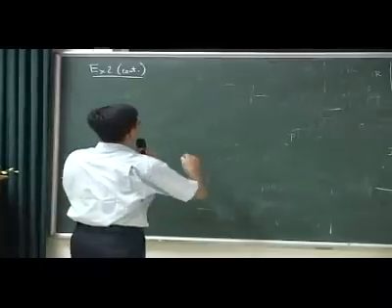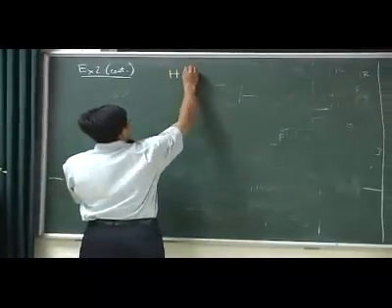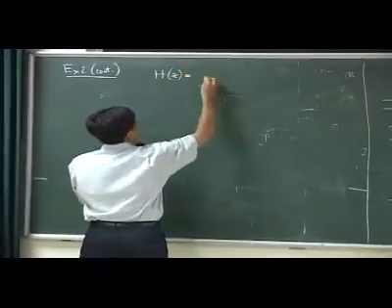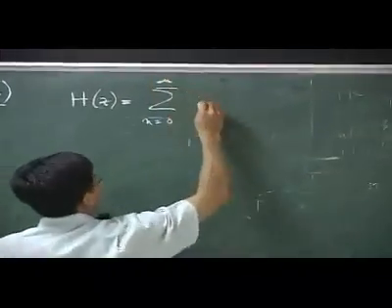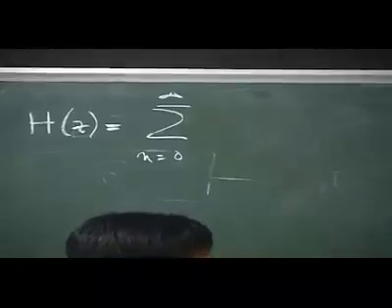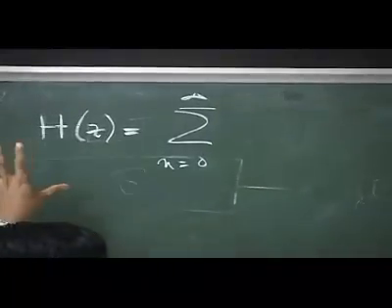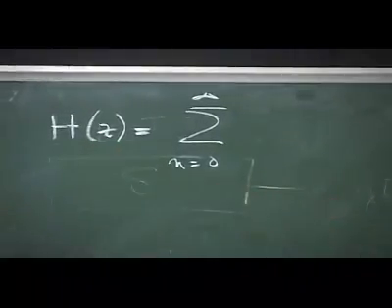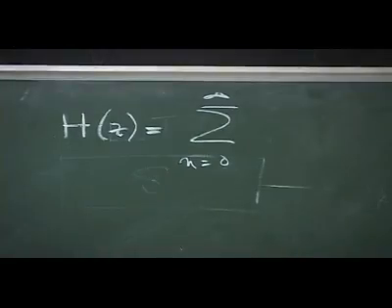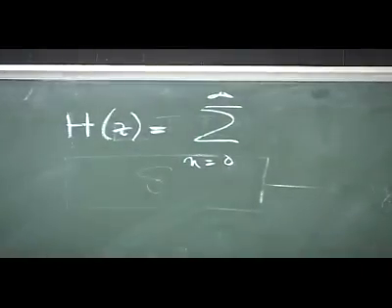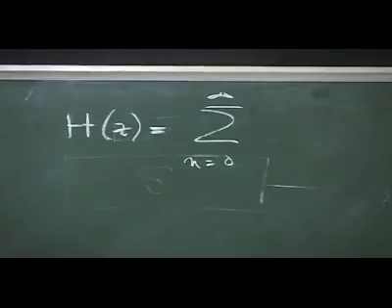So to compute the Z transform, X(z) is now equal to the summation where n goes from 0 to infinity, and I just plug in that signal. Because I have this summation from minus infinity to plus infinity, but from minus infinity to minus 1, the signal is equal to 0, so the sum doesn't contribute.